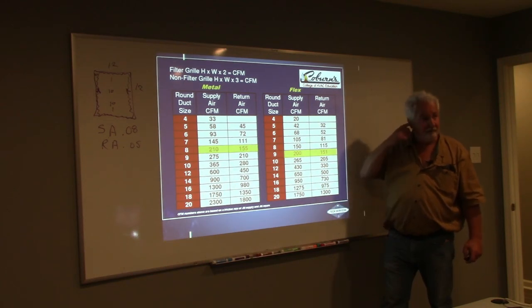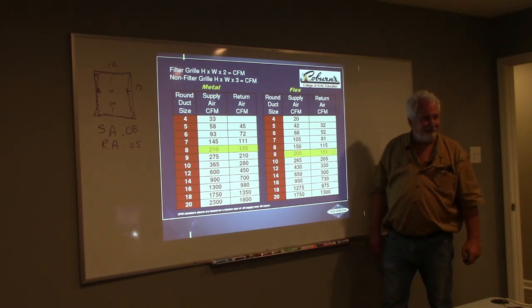Yeah, but the proper way to do that, if you want to get the right amount of air through a 5-ton and a 20-inch flex, is you have to put a flat metal plate and cut it around the 20-inch hole. You have to put an oval box, an egg, on there. And you have to do the same thing on the other side.